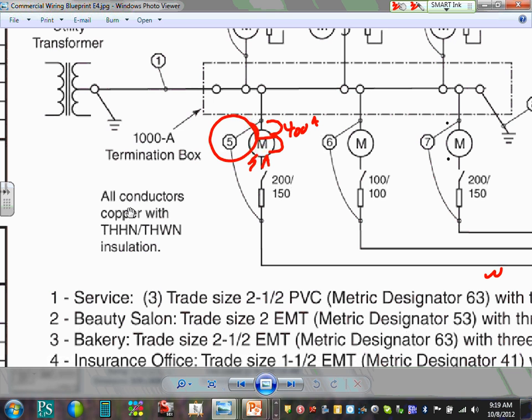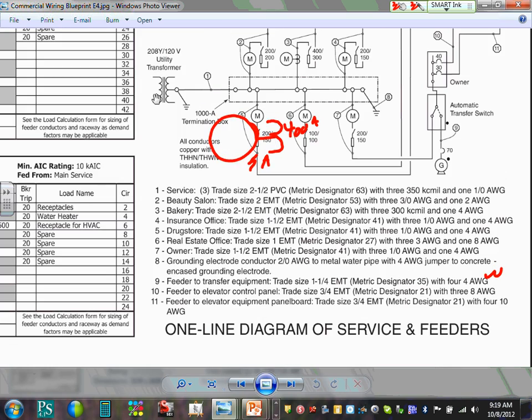So a lot of this is very common, guys. Instead of having an insulation for in and insulation for out, the manufacturer, smarter than Chad, said, how about if you use THHN/THWN? So if you're outside, THWN. If you're inside, THHN. Does it make sense? One insulation for one size conductor. Cheaper way, better way of doing it.